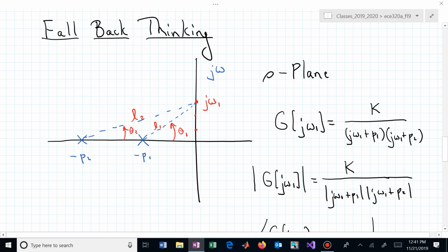Let's say that that result, that magnitude, ends up being 1/2. Then if you inject cosine omega 1 t as an input into the system, what you will see in the steady state is 1, that's the magnitude of the input, times that magnitude of G of j omega, which was 1/2. So your output is only going to be half as high as your input. What's the phase relationship? If you're in phase, the peaks align and the troughs align.